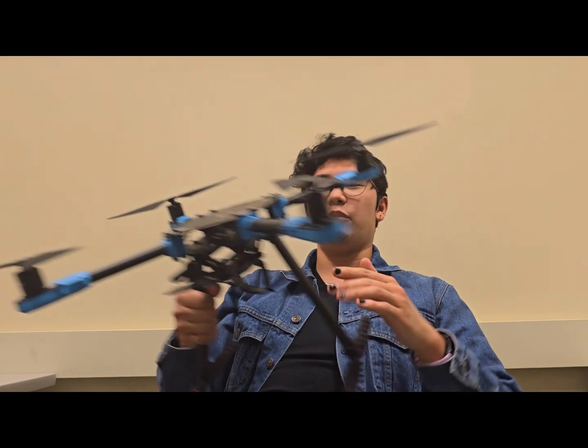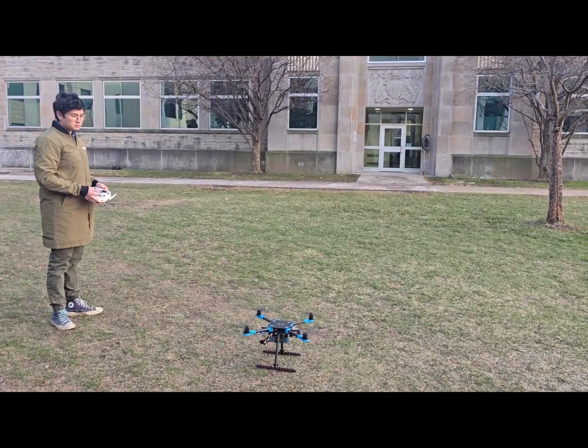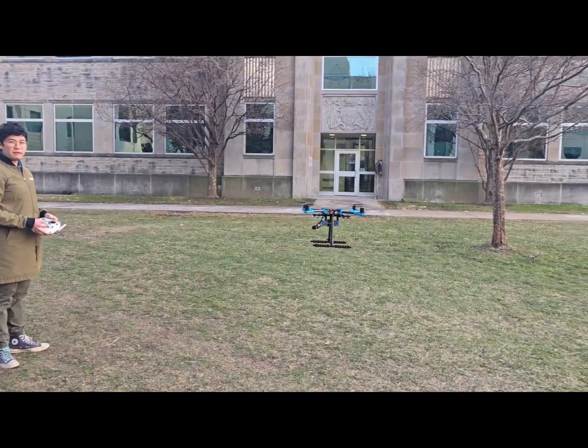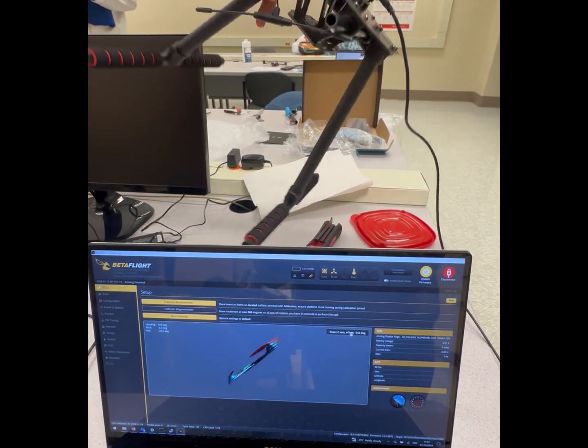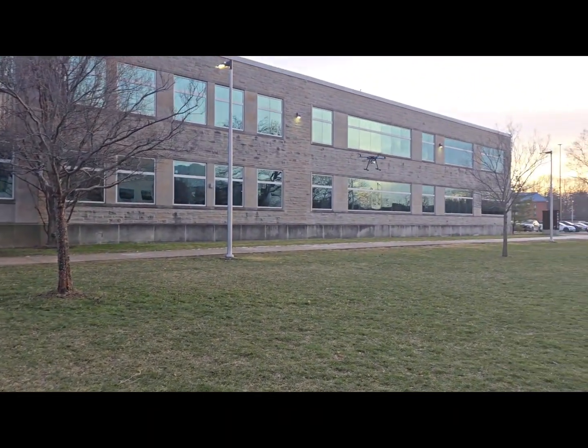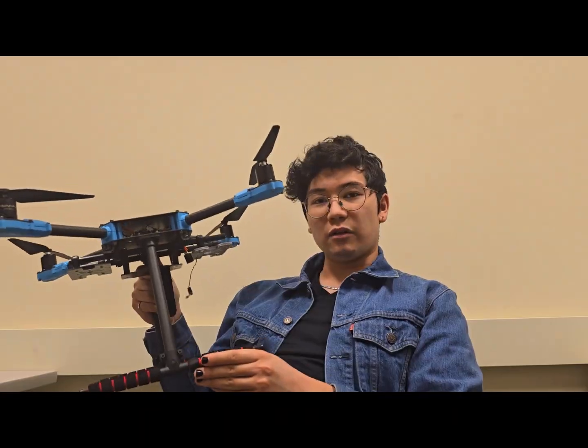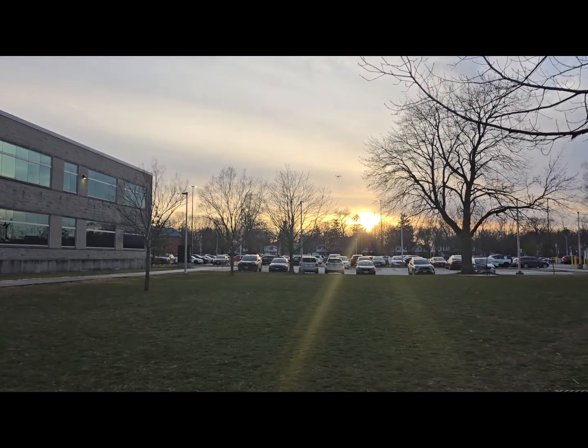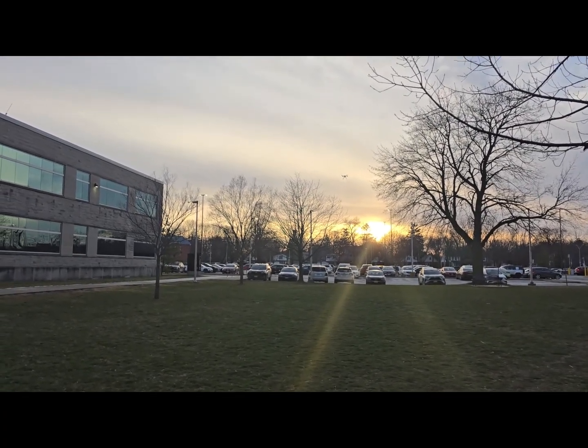This is the drone that we built. For the parts, I picked out an open source flight controller running firmware called Betaflight. I also had to take into consideration what motors to pick, as well as the current limits for the ESC and the current limits for the battery. Efficiency was also something I had to calculate based on the power of the motors running at idle, as well as the payload weight that we needed to carry.